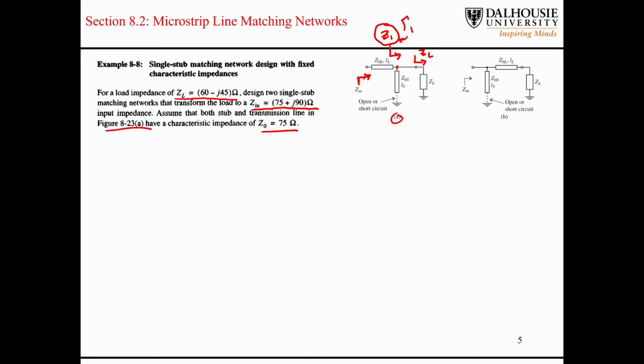coefficient that corresponds to this intermediate impedance, and we're going to have to use that reflection coefficient in order to make use of the constant VSWR circle as we move along this series transmission line here. Okay, so figuring out these intermediate parameters is the first step